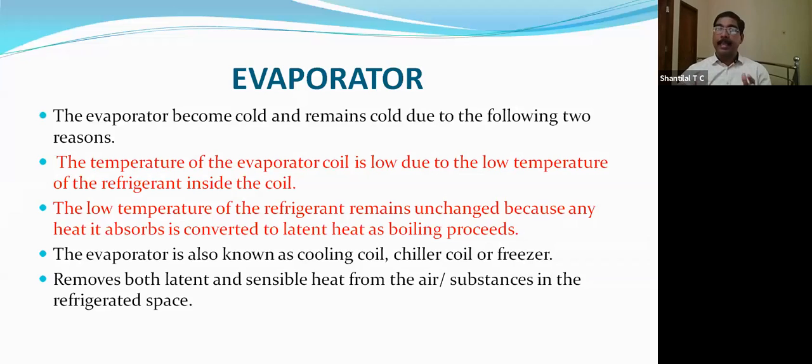Simultaneously, it absorbs latent heat. Latent heat means change of state. The liquid changes to vapor state. By that time, what happened? It will produce cooling. So the evaporator absorbs sensible as well as latent heat from the refrigerated space and produces cooling.